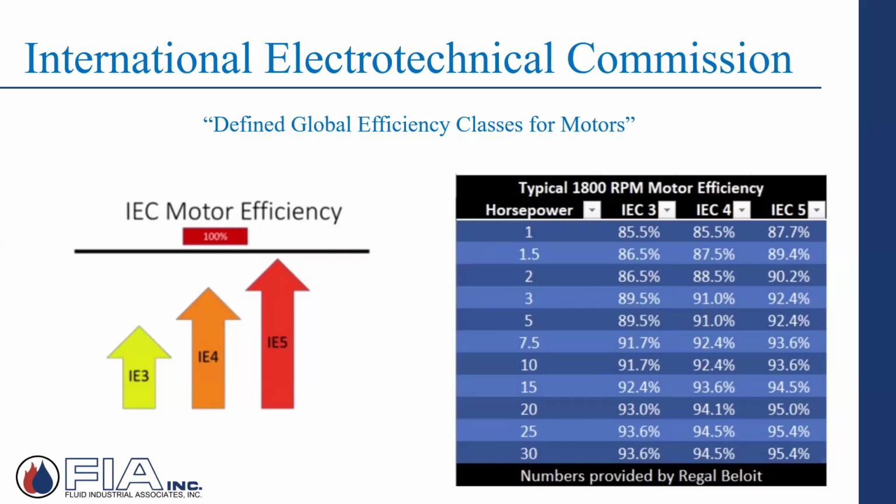Premium efficiency motors with the drive typically classify as IE3, which is still good. It's just that some of this other technology is taking that efficiency and adding a point or two, or a couple of points, to it. So you'll see IE3, IE4, IE5, and that's where I come across some of that terminology, looking at pump specs and selecting pumps.